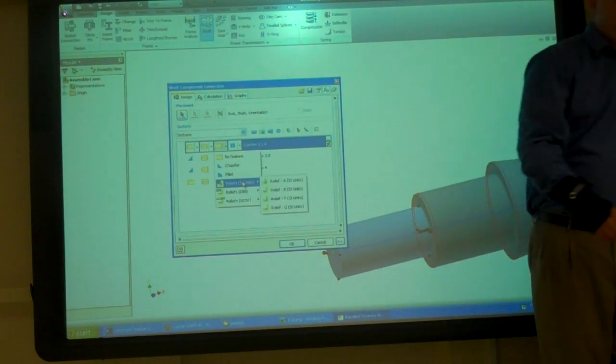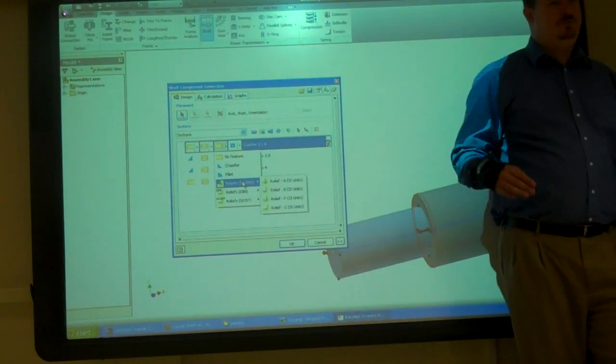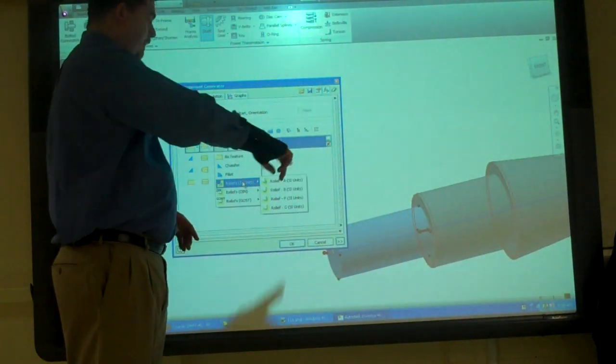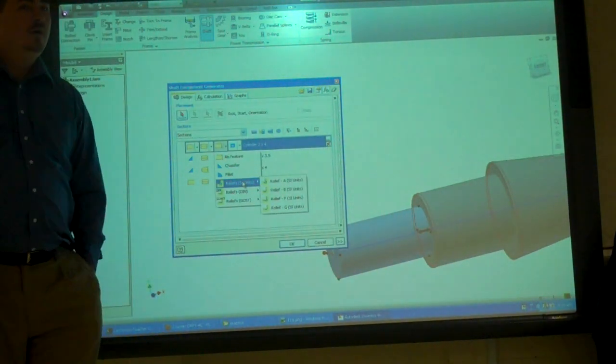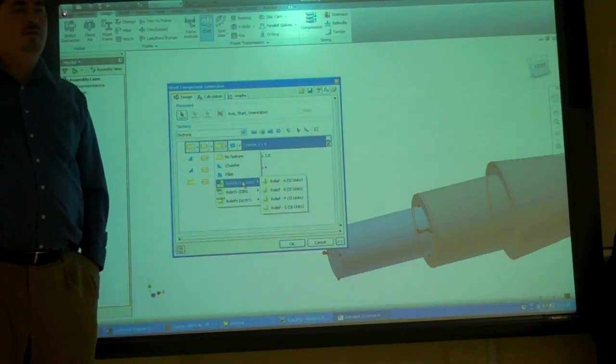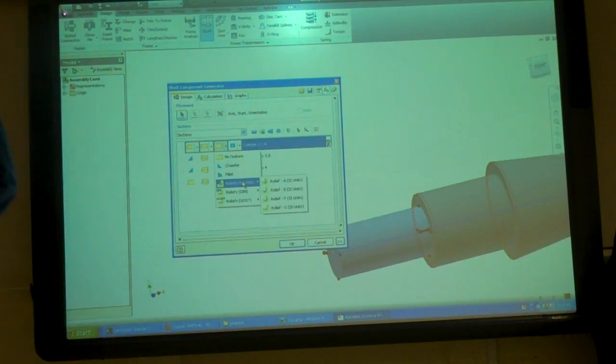But why would we want to do a relief instead of just a fillet there? Because the fillet will be just off by the lathe tool. They always have little fillets on them, so we'd just leave that in there. So why would we do a relief instead of just doing a fillet? Yeah, it's easier to make stuff fit together, right?